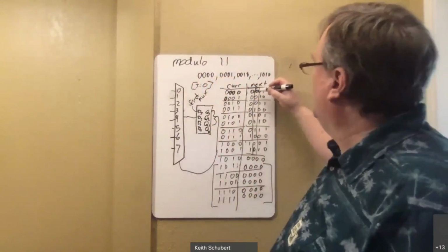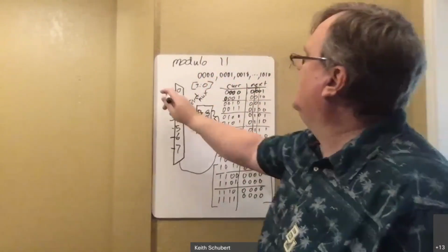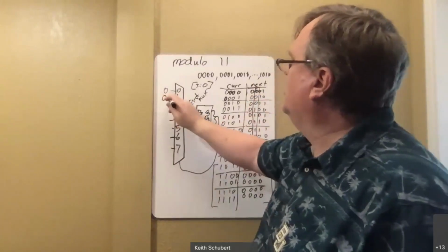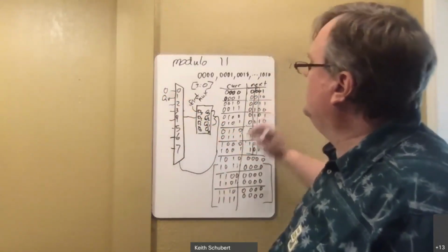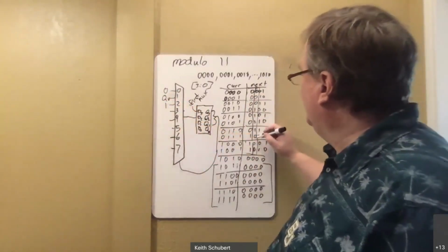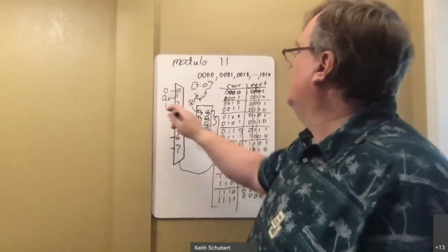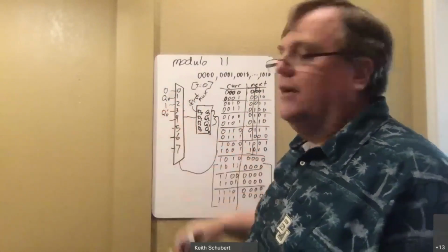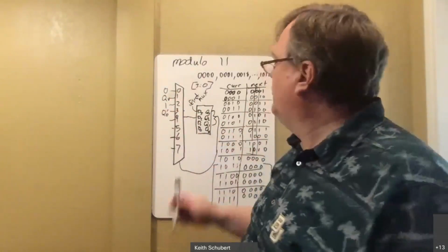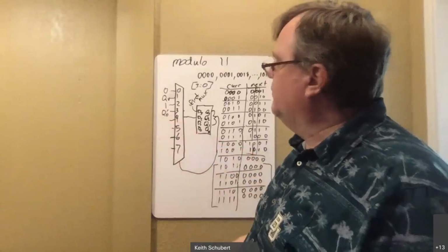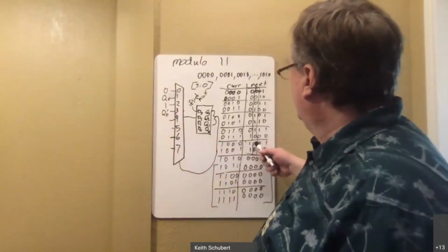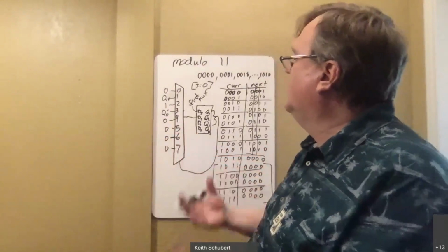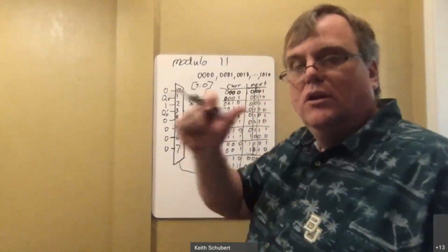We're going to do the second mux, walking through the same way. 0, 0, I get a 0. 0, 1, that's the same as Q0, I put a Q0. 1, 1, that's a 1. 1, 0, that is identical to Q0 primed. If you look in the description of the problem, I said I also gave you an inverter. Then I have a 0, 0, and everything else is zeros, so I can just zero everything else down. And that does the second column. Good with the second column?